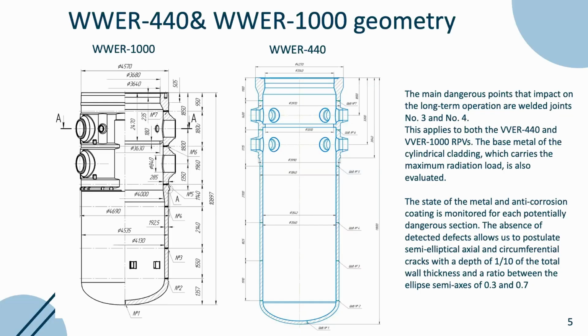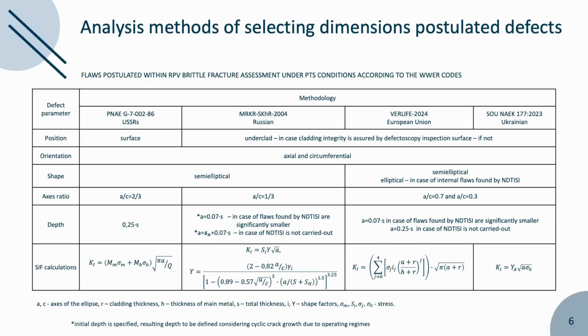This applies to both types of reactor. Using this standard, we can select the size of the defect and evaluate the stress intensity factor.